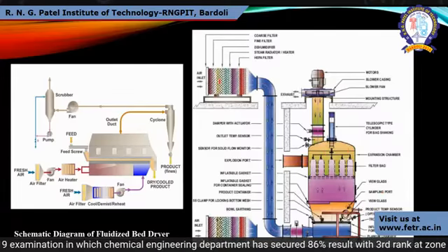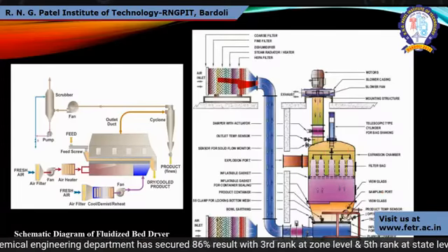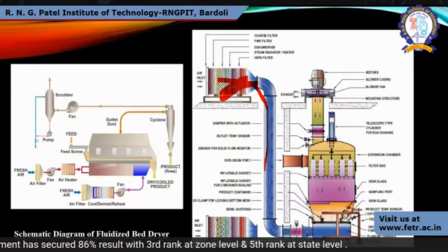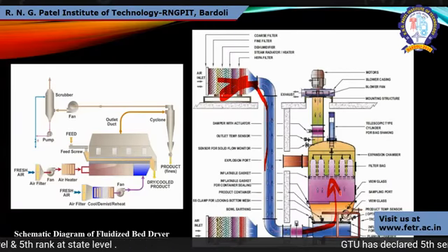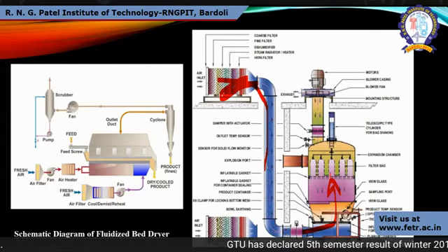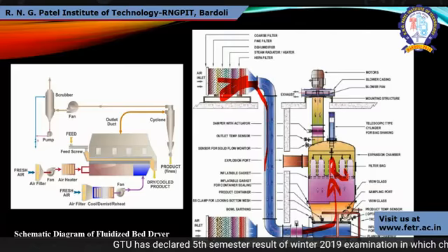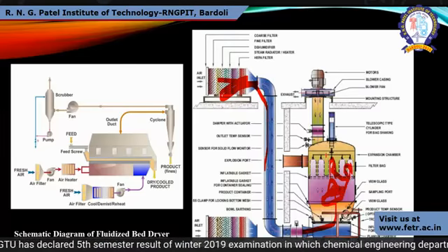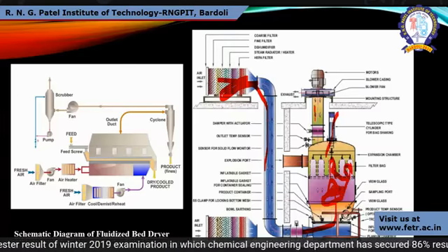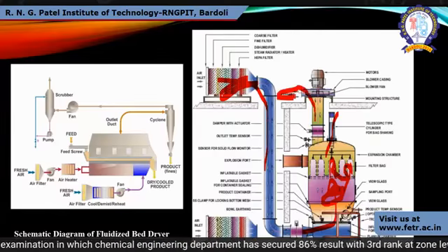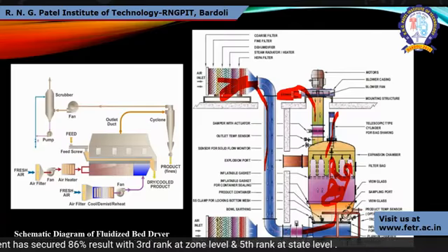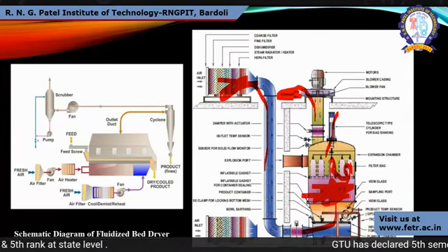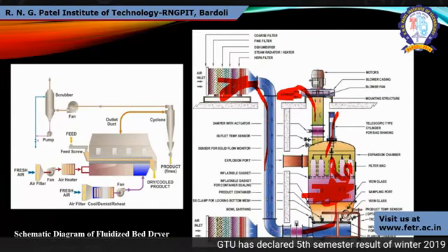See, this is the air inlet, from where air is supplied from the bottom. It goes upward, fluidizes the wet solid, and the solid is collected inside here. Air is taken out as exhaust, the liquid is taken out, and the remaining dry solid is collected over here. So this is basically the fluidized bed dryer.